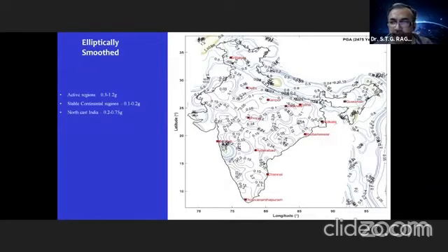So you can see our PGA, that is the Z value, in the Himalayas and Northeast India, the values go from something around 0.3 to 1.2 G. Now in the stable continental regions, the values lie from 0.1 to 0.2 G, except this Koyna region where we will get very high values because of the Koyna earthquake and others. And in Northeast India also we get very high values, something around 0.7 to 0.8 times G actually.